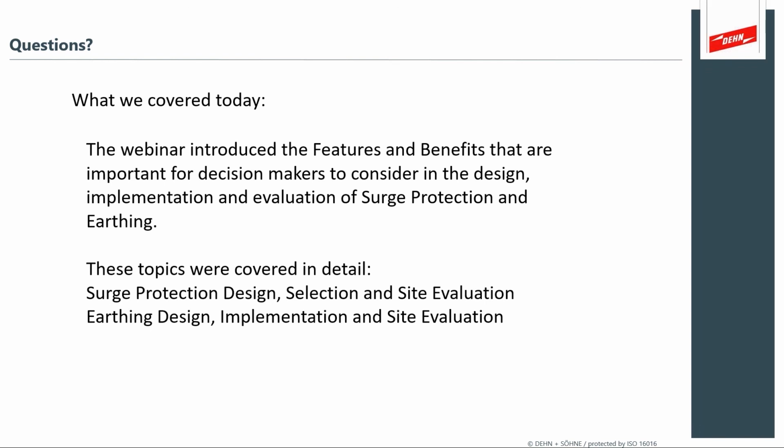Yes, exactly what I wanted to add, Mark, is remember, with older installations way back then, we have more robust electronics, the PCBs and things back then are less electronically driven. So if a client really doesn't have a loss or does not really have a significant risk, I would say you could get away from recommending an SPD for that installation.